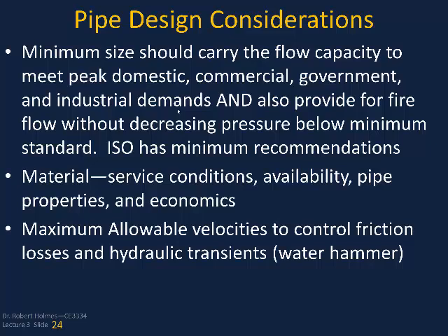And then the last thing to consider on your pipes is maximum allowable velocities. You don't want your velocity so high that you end up setting up a water hammer, a hydraulic transient. If you've ever flushed a toilet or something where you have an instantaneous flow of water, you hear this clanging of the pipes. Well, that's water hammer. That's a hydraulic transient setting up.